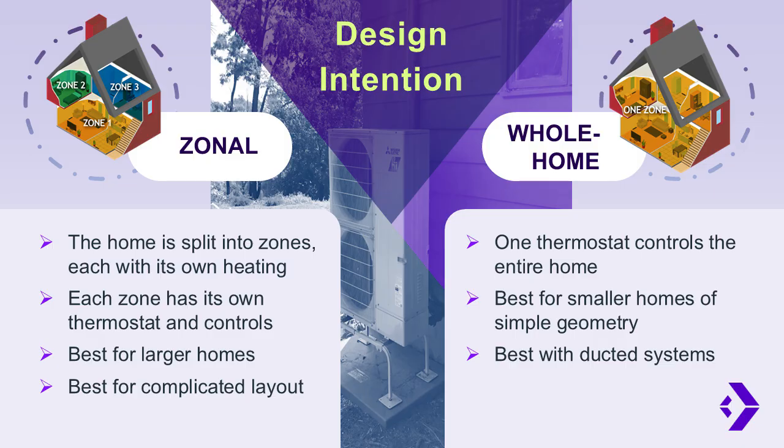On the other hand, a whole home system uses a single thermostat to control the temperature throughout the entire home. This design works best for smaller homes with simple geometry and is often paired with ducted systems for even air distribution. The choice between zonal and whole home design can also depend on homeowners' comfort preference. Taking the time to evaluate these factors will help you create a system that's both efficient and tailored to the